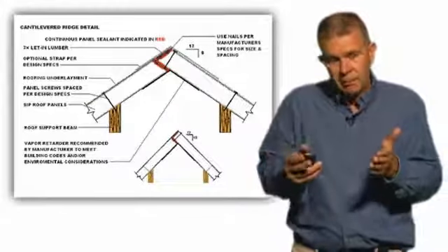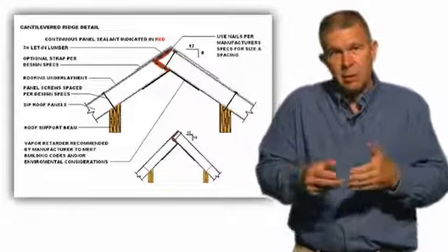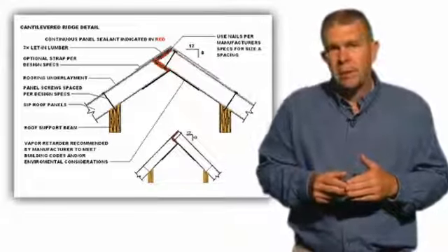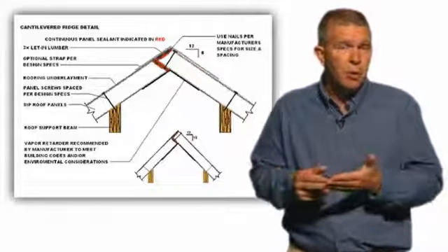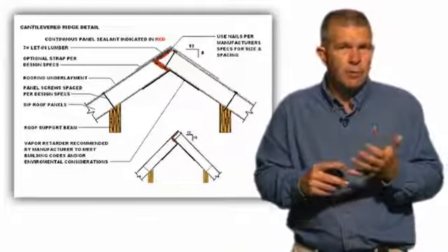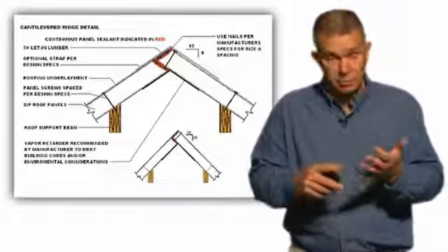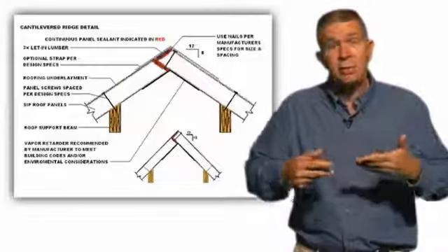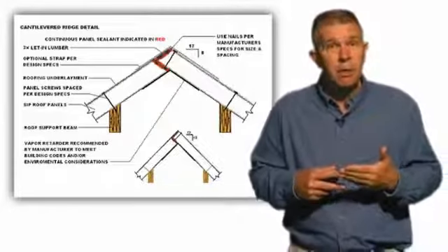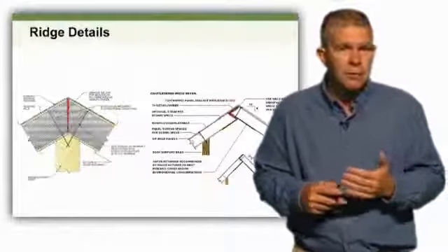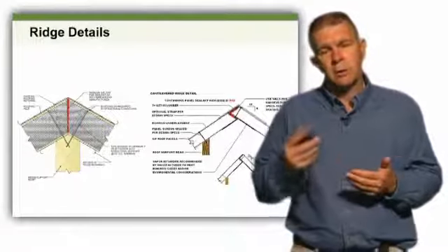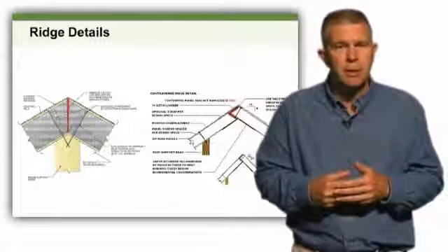detail works very well in not only holding up a roof, but in some cases, once we frame that off, we have a perfect area to incorporate some of the HVAC systems or the electrical components into a conventionally framed false ceiling that works very well to satisfy some of your trade's concerns about working inside of a roof SIP.